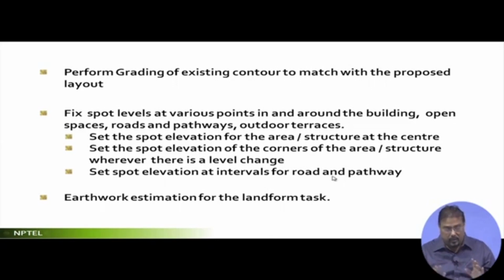So now if I summarize, you have got a project in which, in the landscape, you are trying to make the landform design, and for the landform design first you have studied the soil types, and you will make different divisions of the soils. Once you have done this, you have got the existing contours and the slopes. Now you are going to change it.